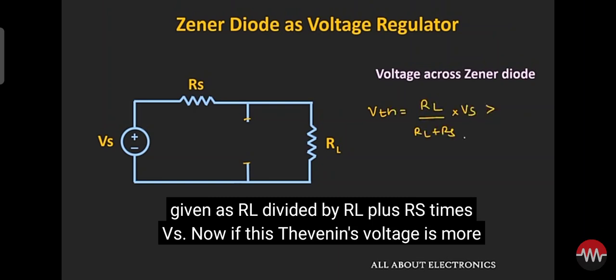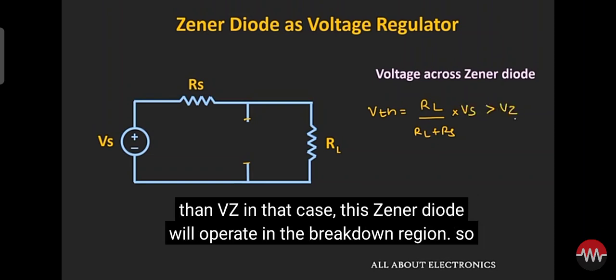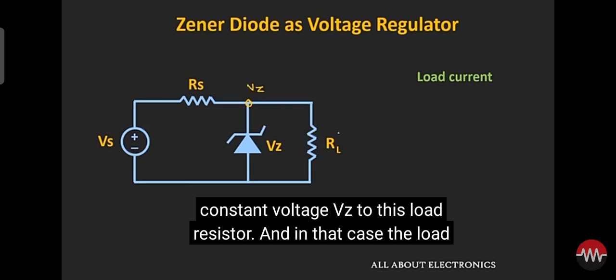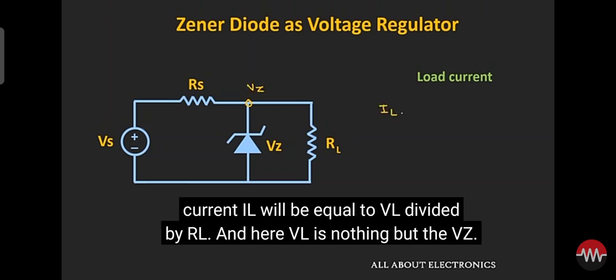Now if this Thevenin's voltage is more than Vz, in that case this Zener diode will operate in the breakdown region. So if this Zener diode operates in the breakdown region, then it will provide a constant voltage Vz to this load resistor, and in that case the load current IL will be equal to VL divided by RL, and here VL is nothing but the Vz.